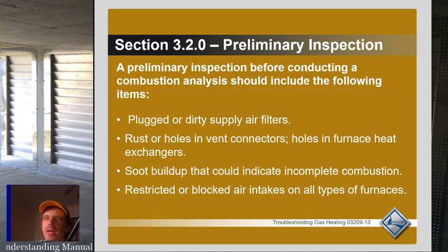Plugged or dirty supply air filters are going to increase the heat inside the combustion chamber, and you're going to end up with issues there. Rust or holes in vent connectors, obviously you may not be venting properly. Or if you've got a hole in the furnace heat exchanger, you're going to have more dilution air, because that air is going to be pushing into the actual combustion chamber.